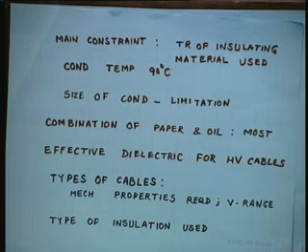How do you find out whether the temperature, the MATR, what is MATR? Maximum allowable temperature rise. This word you should know. When you have done your heating and cooling cycles, those theta maximum curves, time constant for the heating cycle, in the course on utilization of electric power, if at all you have done that course. There you must have drawn those exponential curves, heating and then cooling. There the heating should not cross the maximum allowable temperature rise.